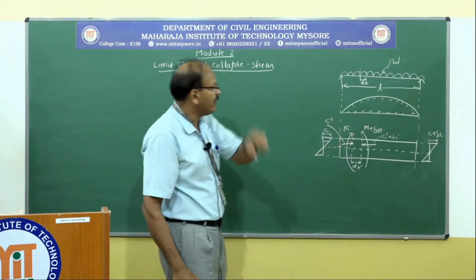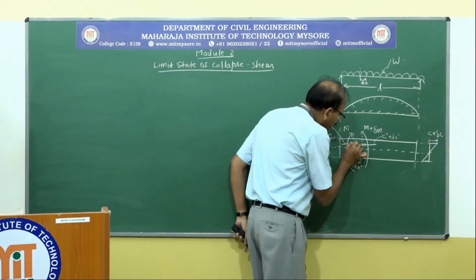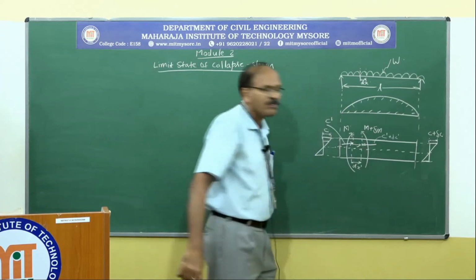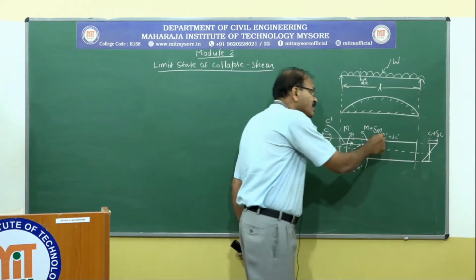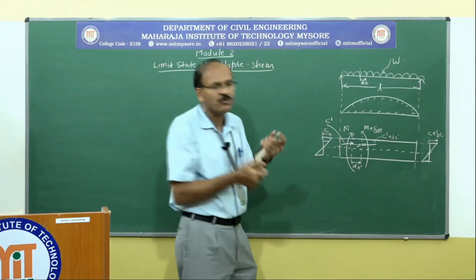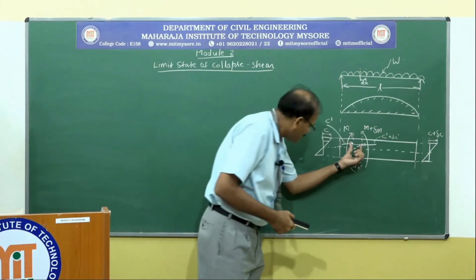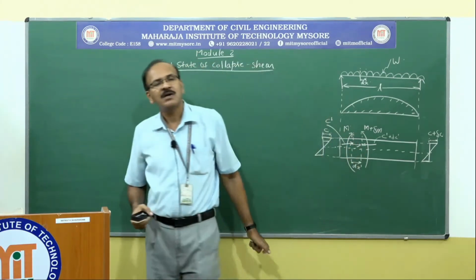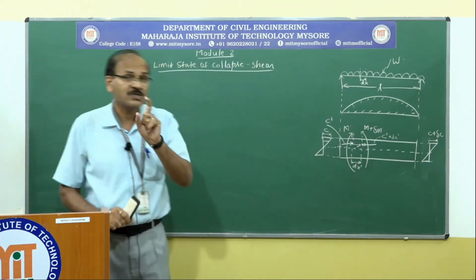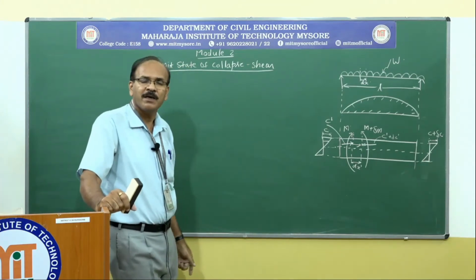To maintain equilibrium, there is going to be a stress of magnitude C dash plus delta C dash minus C dash, that is going to be delta C dash. So this imbalance of force or stress gives rise to shear stress.